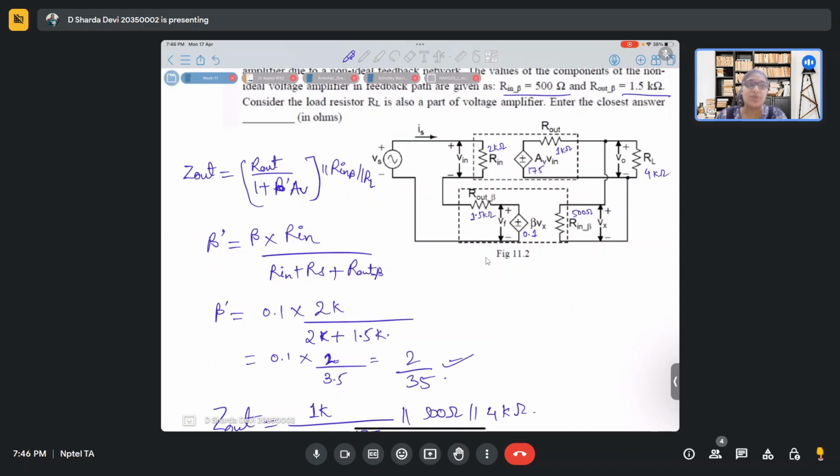But coming to gains, gain always reduces. Whether it is current gain or voltage gain, it will always reduce. But for impedance, it is actually improved with the closed loop. So compared to open loop, closed loop impedances are actually even better. It manages the impedance.